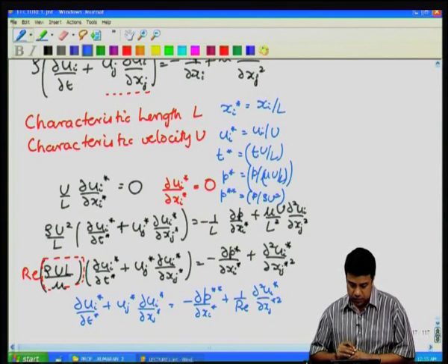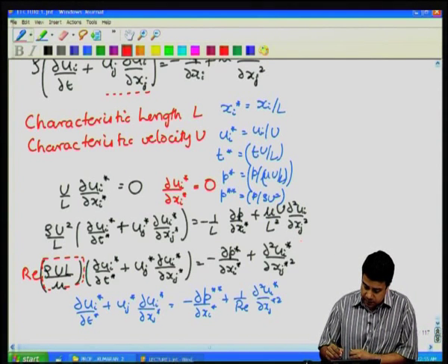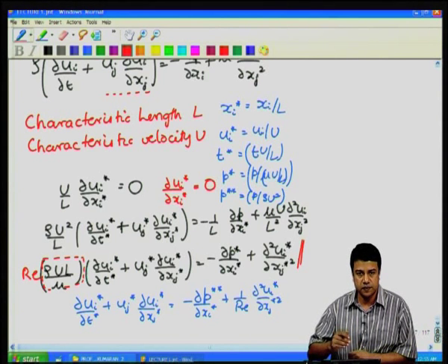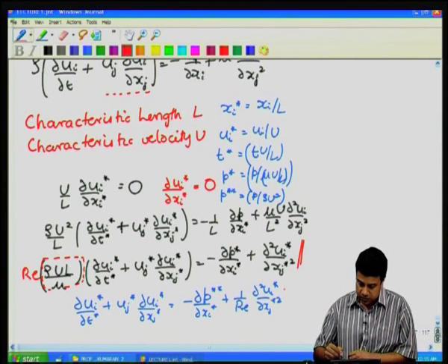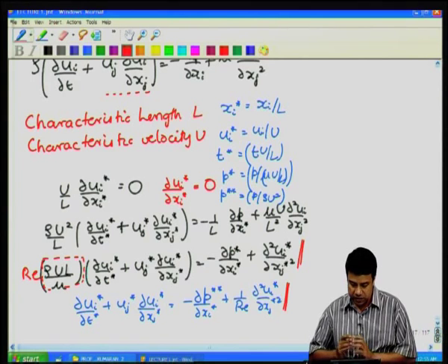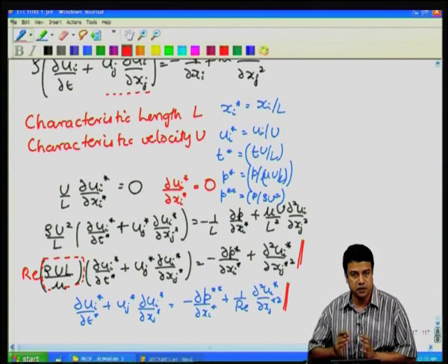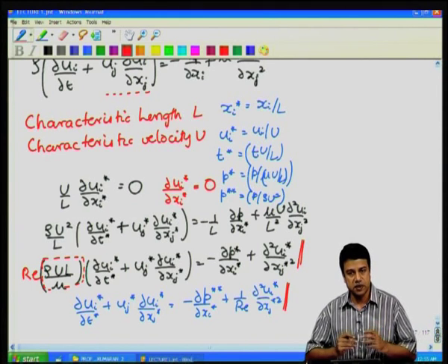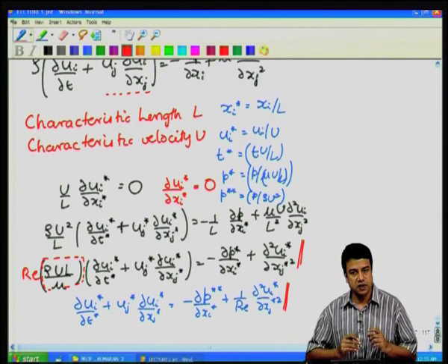Okay. So, the first equation you would use when you expect the viscous forces to be dominant: I have a Reynolds number times the inertial forces equal to minus pressure gradient plus viscous forces. The next you would use when you expect inertial forces to be dominant, so that you would expect a balance between the inertial forces in the equation and the pressure gradient.